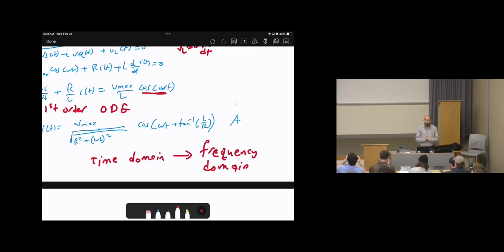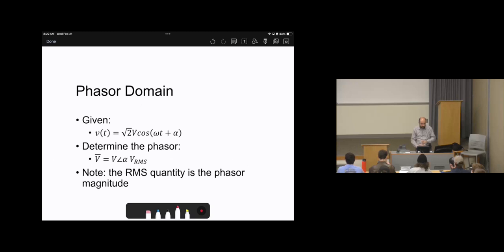While here, instead of converting a math equation, we will convert the electrical elements. So let's convert the voltage source, current source, resistor, inductor, and capacitor. Then we will do our own version of transformation, so we can use it to solve the circuits. We realize that when we convert the system into the phasor domain, the AC circuit will be very similar to DC, such that we will have constant voltage and constant currents.